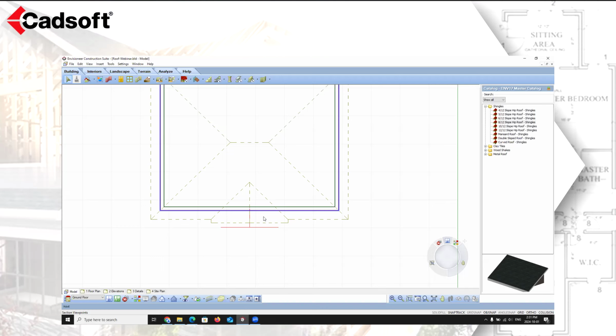Use the Roof by Picking Points tool to create a roof of a custom size and shape that is independent of the walls beneath it. This method is ideal for veranda or shed roofs. General editing tools like Move and Rotate apply to the entire roof itself. Use the grips on a roof's corners and edges to resize and reshape the roof. Each roof segment can be edited individually. By editing the properties of different segments, you can create a roof with multiple pitches, plate heights, and styles.